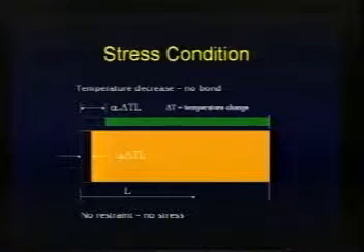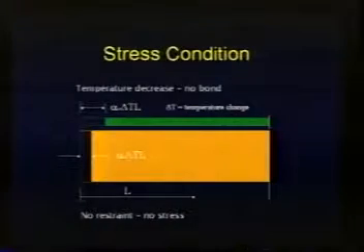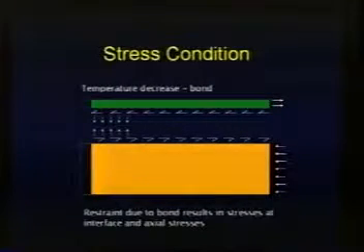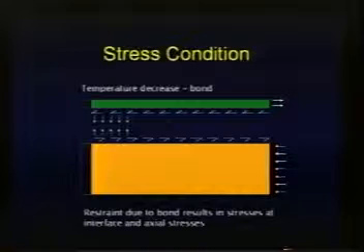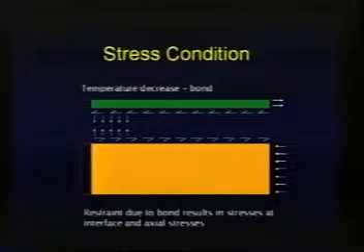And so if you look at the green slab there, you'll notice that the change in dimension is greater than it is for the yellow concrete slab, because again reflecting the fact that the coefficients of thermal expansion are normally higher. And we find they're anywhere from about 50% to maybe 200% higher, 250% higher than concrete. Now, obviously, we don't want that situation. We want the polymer concrete to be bonded to the Portland cement concrete. So what happens if we bond the polymer concrete to the Portland cement concrete and we get a temperature change?